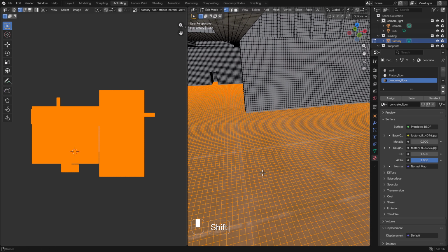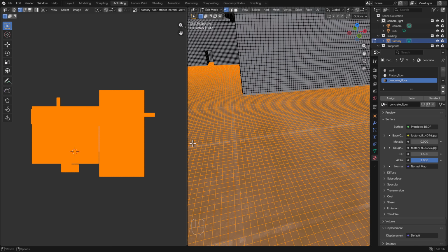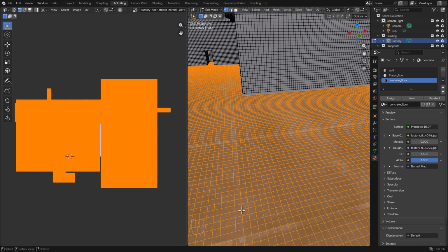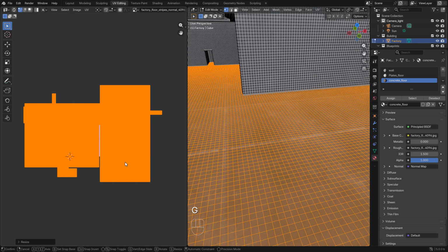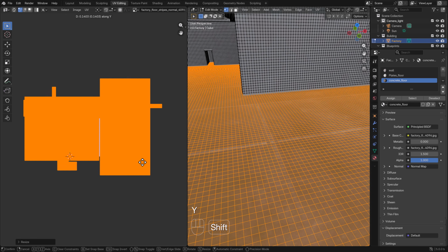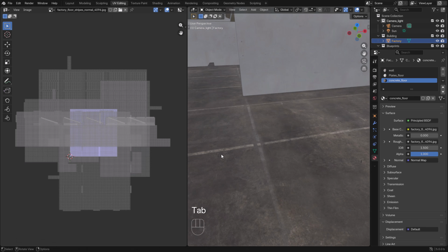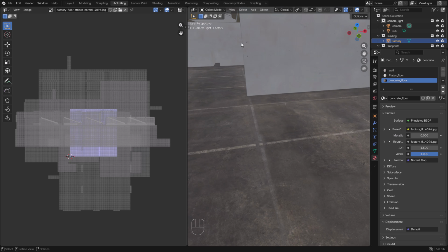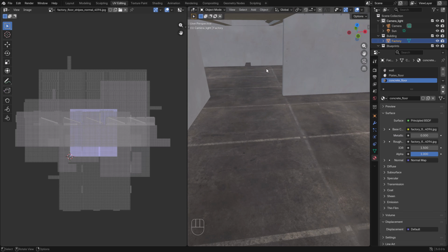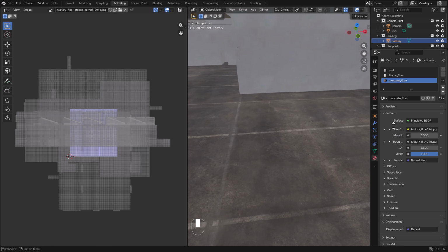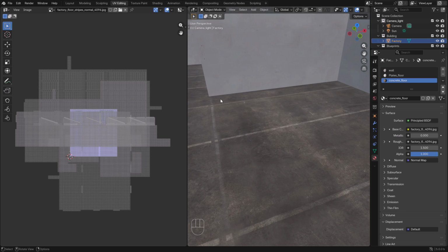It's hard to see where the texture is because it's highlighted, but what I like to do is move this white stripe to the right, and make it a little bit smaller. Pressing GX or GY, and holding Shift. And I want to have this white line connecting with the end of this wall, because this area to the end will be a different material. So I don't like how it's ending right there.